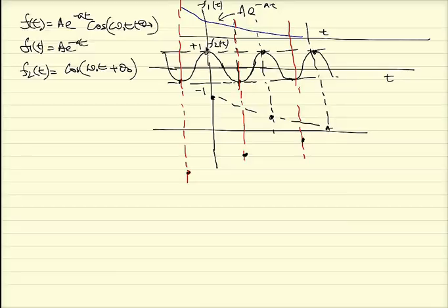Now here, as you see, we have tried to plot why we have the shape of the decaying exponential signal. This is the main signal equation. It has two parts. f1t is the exponent part, e to the power minus at, an exponentially decaying signal, which is shown here, f1t versus t. And then you have f2t, which is a cosine wave with a theta naught.